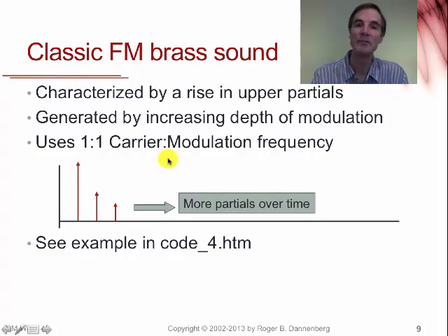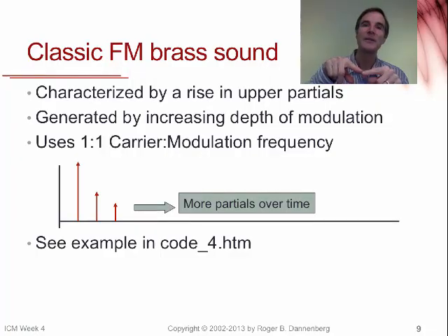We use a 1-to-1 carrier to modulation frequency so that we generate harmonics, and we rapidly increase the depth of modulation. Again, let me remind you, when I say depth of modulation, that means how many hertz the carrier is increased by and decreased by through the frequency modulation.